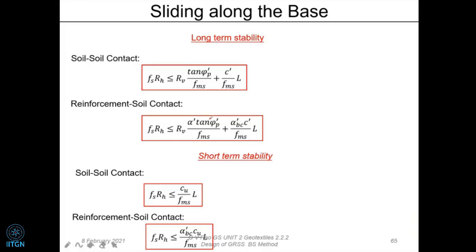One thing that happens is, if you are using a geotextile, there are two contact surfaces, because there is soil at the top and soil at the bottom. So interaction is happening at the bottom of the geosynthetic and also at the top of the geosynthetic. If it's a geotextile, that means twice the friction angle. In the other case, we have a grid. Grid means natural interlocking is going to help us. So in the case of a grid, the interaction factor is going to be single only, because it considers the interaction between the aggregate or fill material and the geogrid.